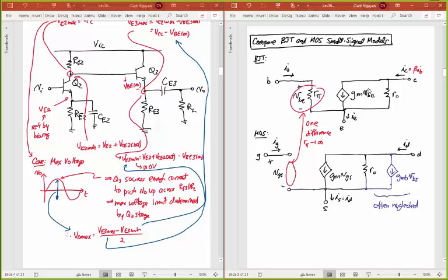Right? For an MOS transistor, what is IG? It's equal to 0. At least at DC, it's equal to 0. And so I'm getting some finite current ID. If I wanted to say ID is equal to beta times IG, then that beta is going to have to be infinity. And so this R pi going to infinity really comes from beta going to infinity, because beta going to infinity means that R pi, which is equal to beta over GM, also has to be infinity. Okay, so that's one difference between MOS and bipolar junction transistors, that you have an infinite beta in the MOS case.